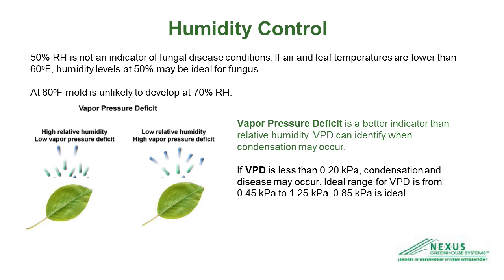And that would cause your plants to break out in powdery mildew and maybe even reach the dew point temperature and have fungal problems. And a great majority of this has to do with very poor mixing inside these warehouse environments and then poor controls for sensors.